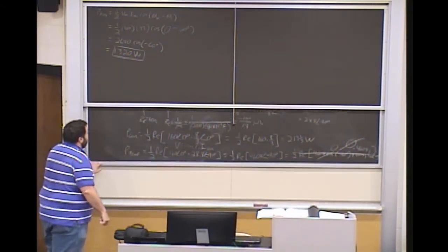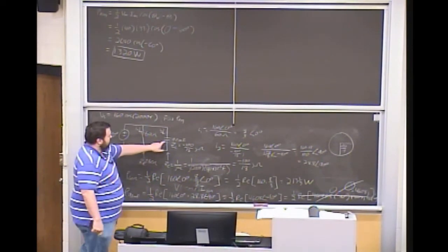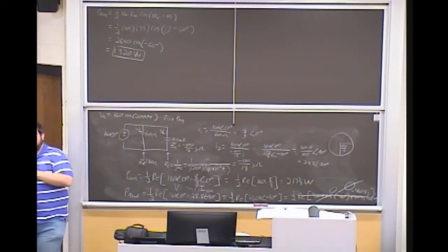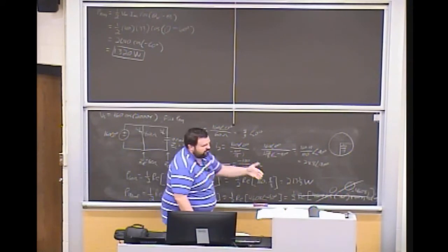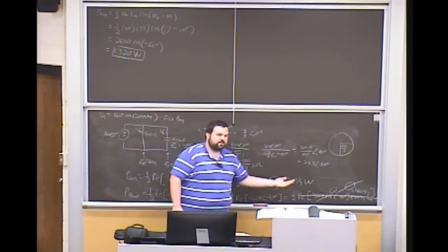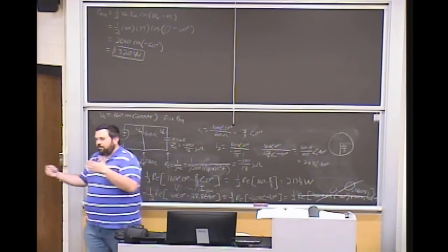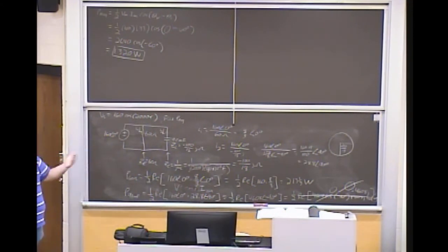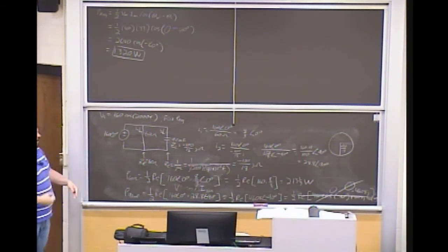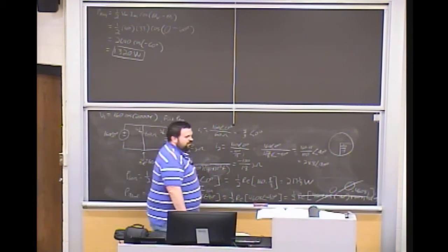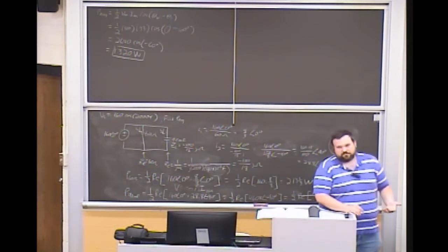So when I go back to what I actually had here, a purely capacitive load on average dissipates no energy. Why? Because effectively when you have AC, you have this charging, discharging, charging, discharging. And all of your currents and all of your voltages basically balance out. You give it charge, and it gives it right back. And so when we're talking about power being dissipated, power is really only dissipated when you have resistive loads.